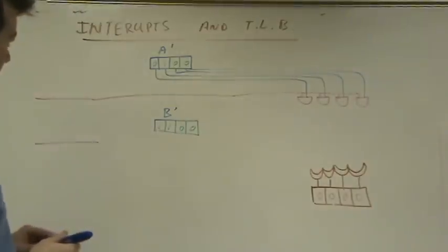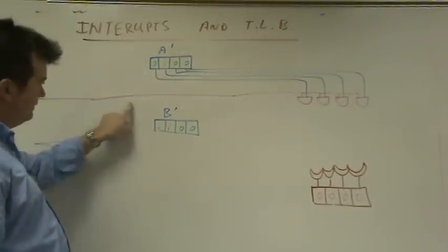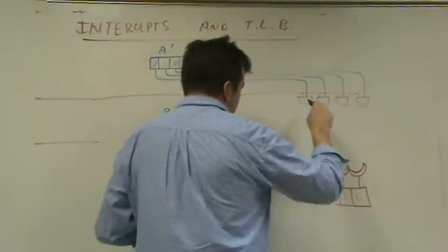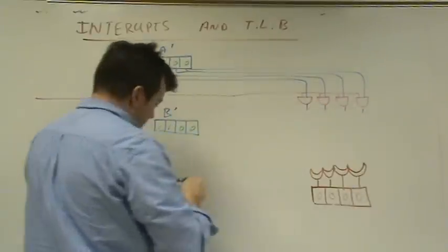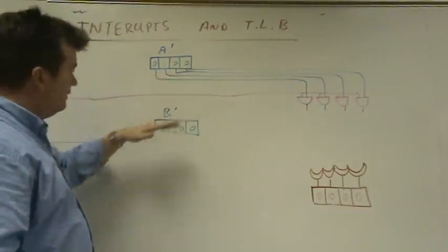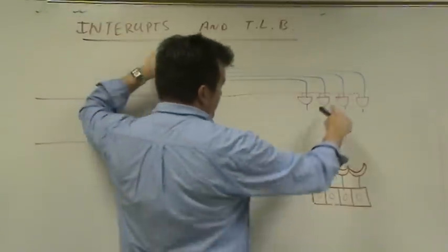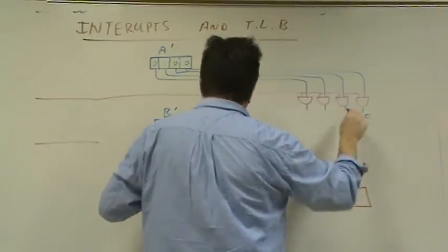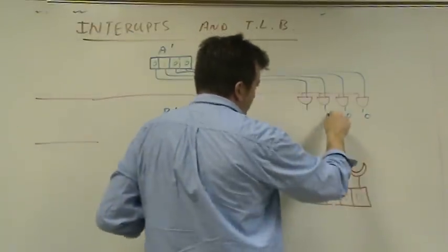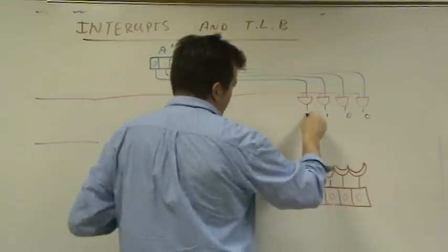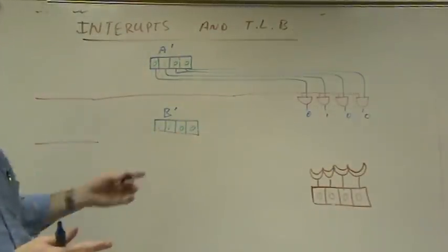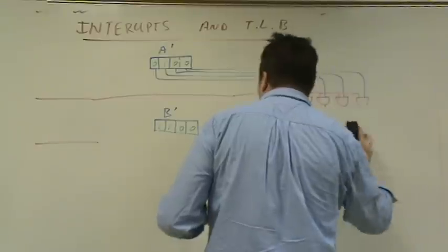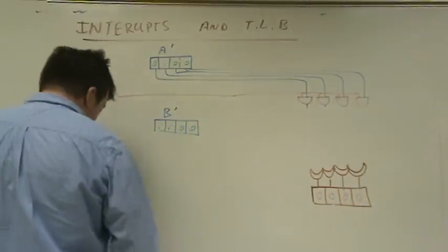Okay, so if this line right here is on, then these outputs should be this register, right? If this is on, then this being a 0 means this came out 0. This being a 0 and this 1, this came out a 0. 0, 0. This 1 and this 1 came out a 1. And this 0 and this 1 came out a 0. So basically, it would just copy the value of the register over. Okay? We did the same thing twice, and we did the same thing for this one.